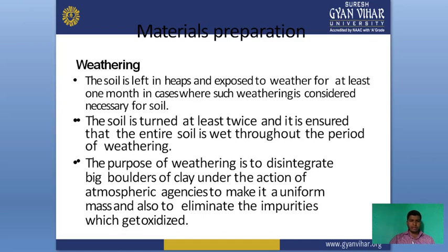Weathering: the soil is left in heaps and exposed to weather for at least 1 month, in case such weathering is considered necessary for the soil. The soil is turned at least twice, and it is ensured that the entire soil is wet throughout the period of weathering. The purpose of weathering is to disintegrate big boulders of clay under the action of atmospheric agencies to make it a uniform mass and also to eliminate the impurities which got oxidized.